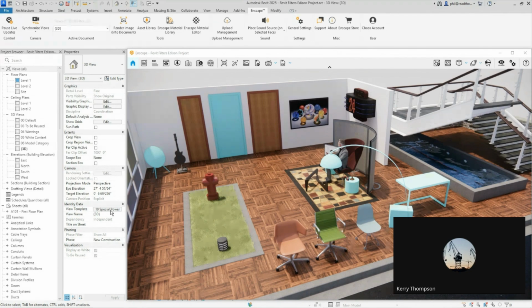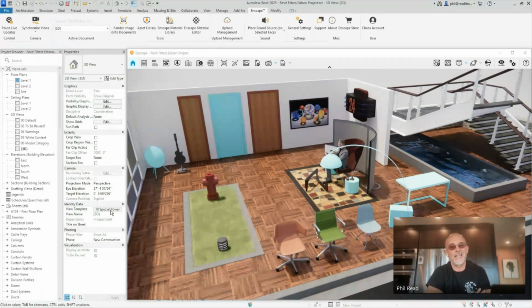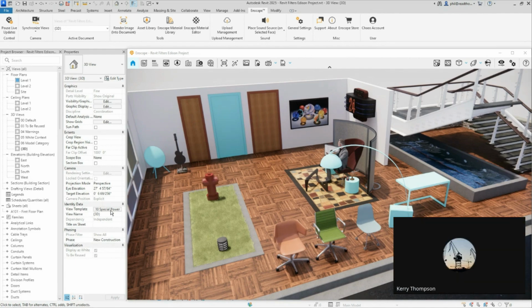So if you wanted to make all the linked files green, for example, you just run a category, make all the linked files green as a Dynamo script. And yeah, that's one thing I couldn't find. And you can't do linked files. You can't apply filters at the moment to linked files anyway. So you can't say, oh, make this link this color, this link this color. Just like a quick way to. You might be able to do.